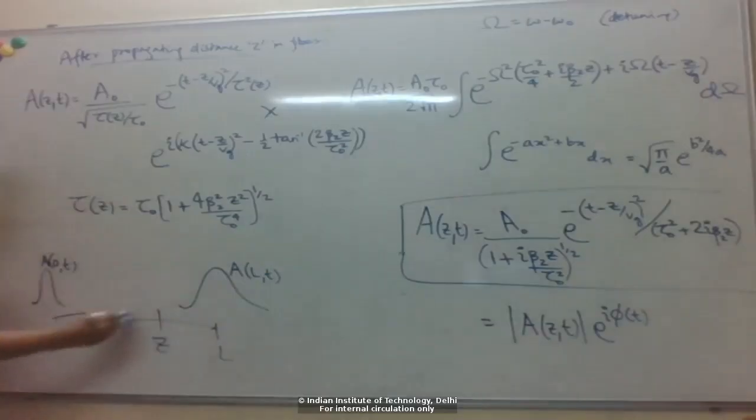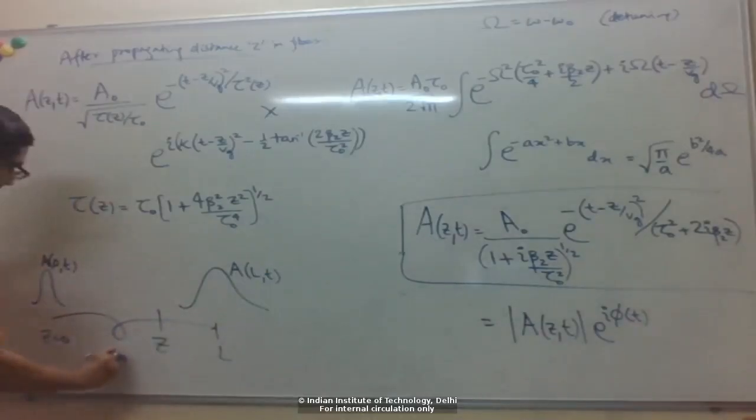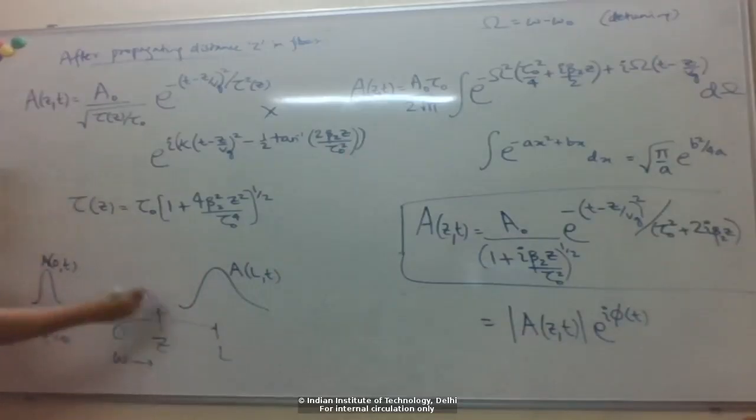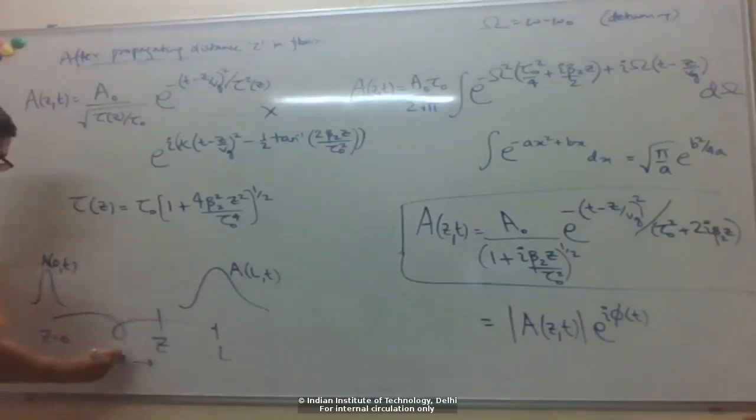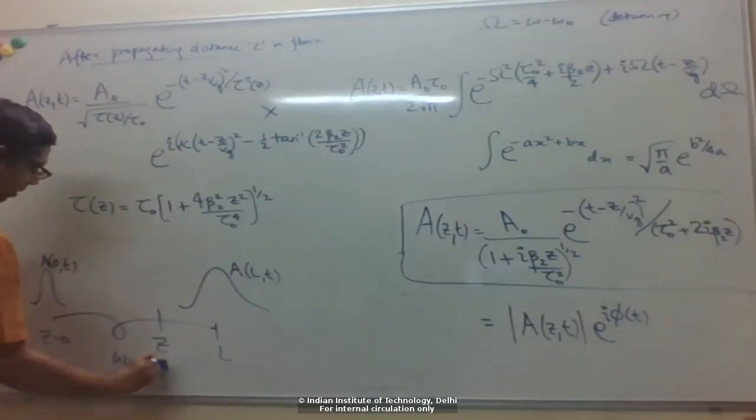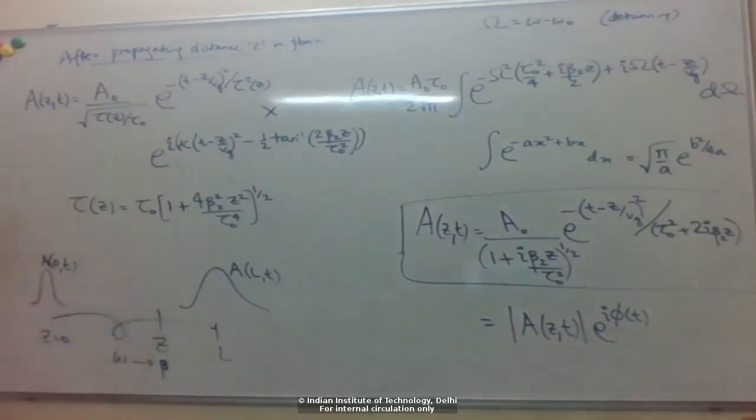What we know already from modes in the fiber is that for any particular frequency, given the particular mode, we have a particular propagation constant. For example, in single mode fiber, only the LP01 mode will be there, and we have a b-V curve. Given a particular frequency or V number, we know what the propagation constant would be.